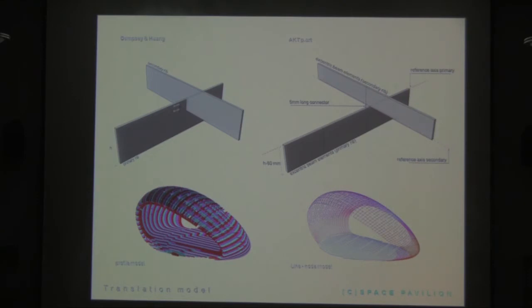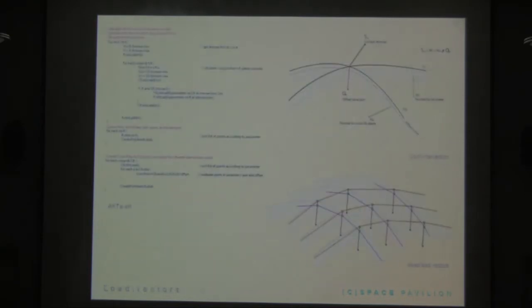Our structural engineers, AKT, developed a really innovative C# plugin, which was taking our Rhino node and point network and looking at the way that we intersected and the way they intersected. They're only looking at how those eccentric beams intersect at the nodes and not how they overlap. And they're taking those nodes and basically sizing them off of those structural loads to give us a structural depth.